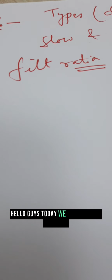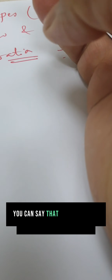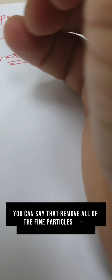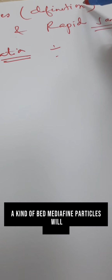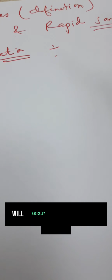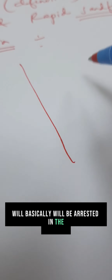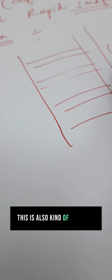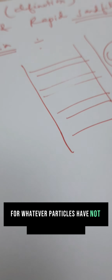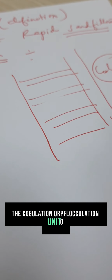Hello guys, today we'll learn about the term filtration. Filtration is nothing but the removal of fine particles using gravels, or a kind of bed media. The fine particles will be arrested in the different layers of the packing materials. So this is also a kind of column. Whatever particles have not been removed by the coagulation and flocculation unit will be removed by the filtration.